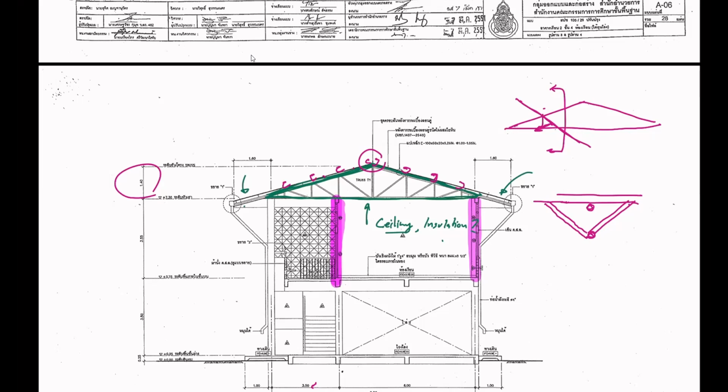There are two ways to consider the wind load right now. First is by using the standard that you are referring to. The second is by using the good old Building Act, which simplifies the wind load into just some constants that depend on the height. In real life, if it's a steel structure, you should consider wind load because of the nature of the discontinuity in the members. You need to form the frame out of members.